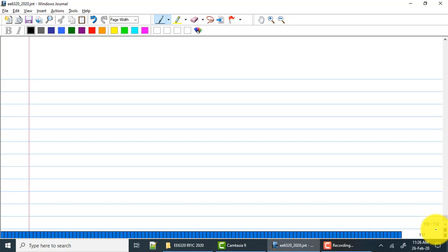I'm not comparing this with the common source LNA. I'm comparing this with the common gate LNA. This will definitely be better than a common gate LNA. The advantage of this circuit is that it's broadband. This can work all the way from baseband to a couple of gigahertz easily.